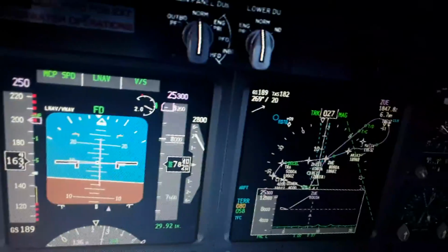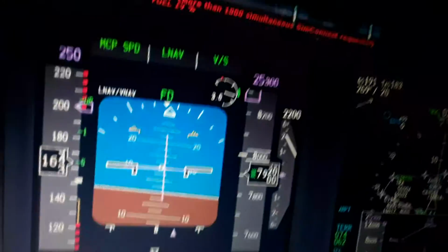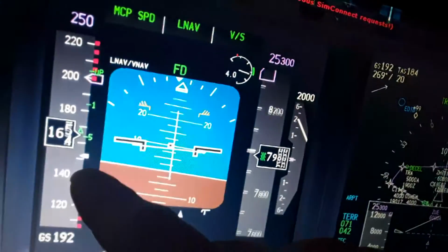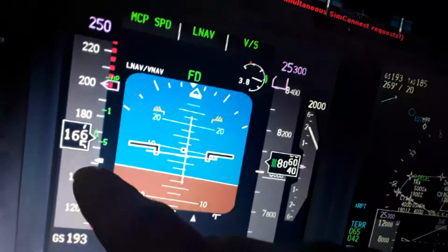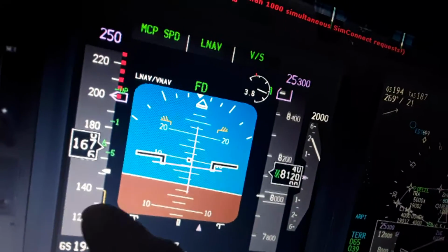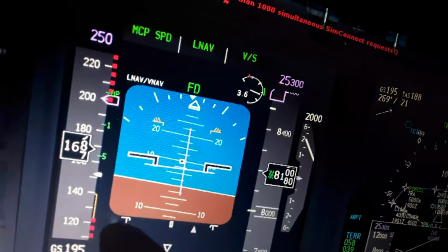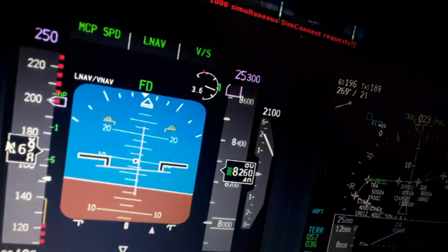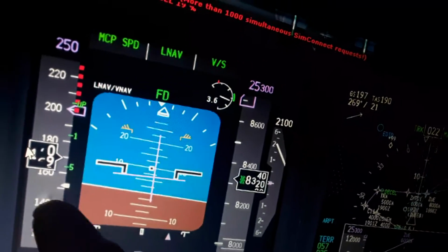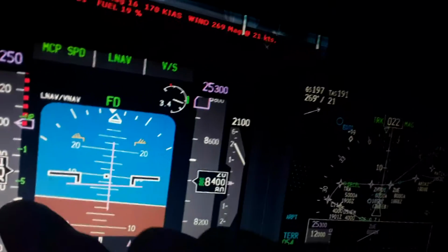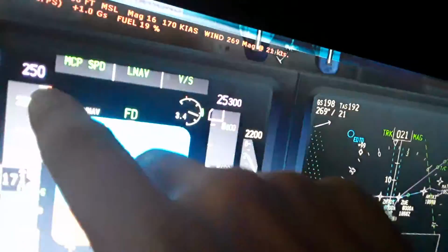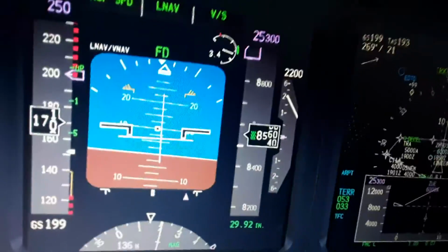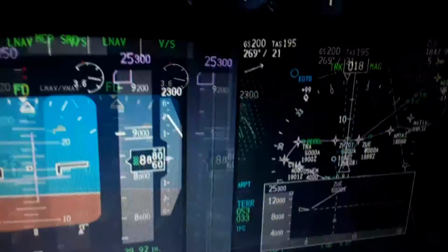You can see we almost reach our stall speed. We have a very narrow buffet, lower airspeed, which is gonna stall the aircraft. Here on the radar, 122 knots maybe. And this is a safe speed of 140 knots that we have to avoid. Here the upper limit is the flap speed because we have flaps extended right now. You can see the auto trim is trimming the aircraft now based on the auto thrust demand.